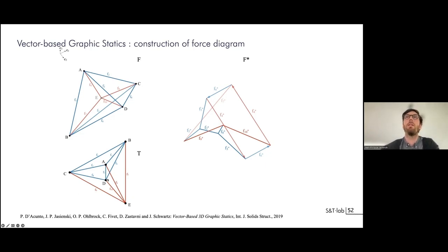So the strategy to assemble the force diagram is to planarize this graph, which means adding nodes. This is so that in the end, we will have non-overlapping bars. If I add a node here, then F6 and F4 are split in two elements, and that's why they will be represented twice.